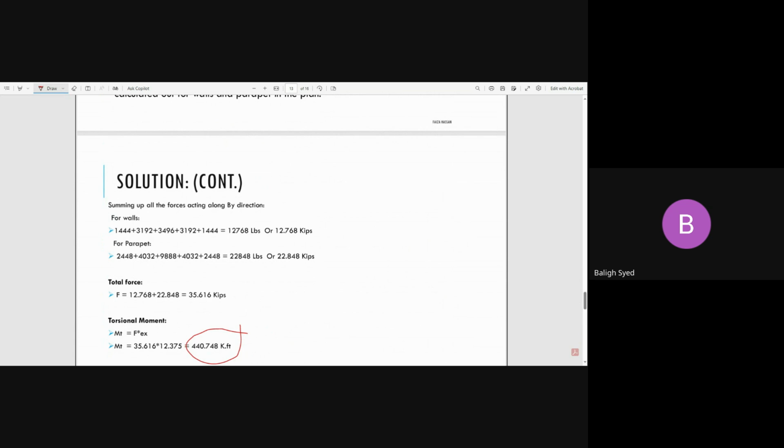Then you calculate the wind torque on your structure, and then you check it. At the base, if the base shear is making sense and matching with your sanity checks and hand calc outputs, then it is making sense. Otherwise, nothing is right. Literally, otherwise nothing is right. Modeling is nothing. It has to make sense. You have to feel accurate.